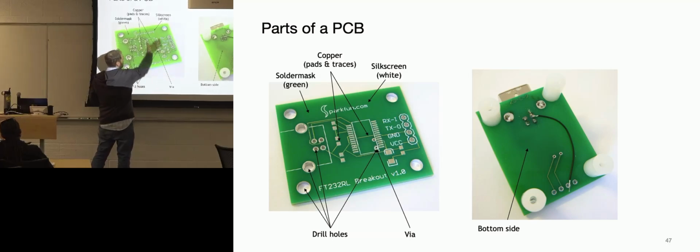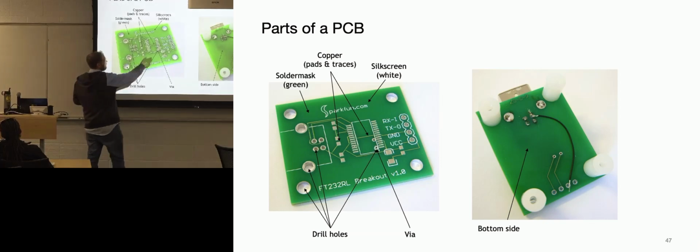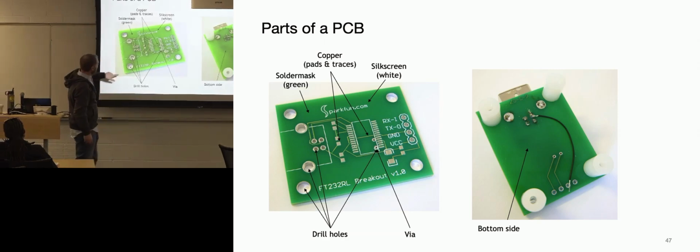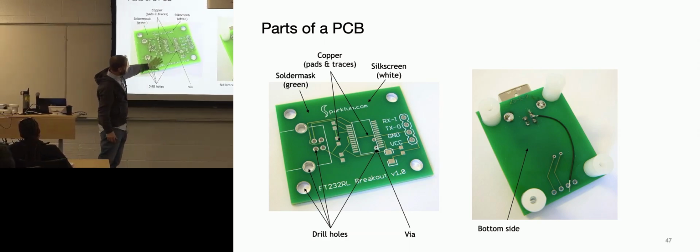And then this is also a surface mount dual inline package, where you would put your chip on here and solder it up. Usually PCB is a tan color, and then they'll put material color over it. This is the solder mask. What it's doing here is you have a pad, and this is tin copper. Tin is a material that keeps the copper from oxidizing. And then you can see this trace here is actually greenish. That's because they put the solder mask over everything except for that pad. And so this protects solder.